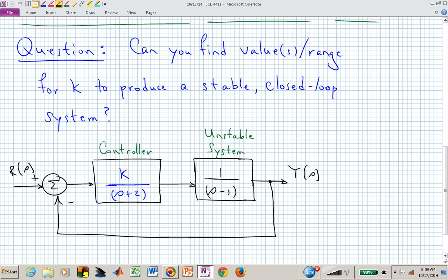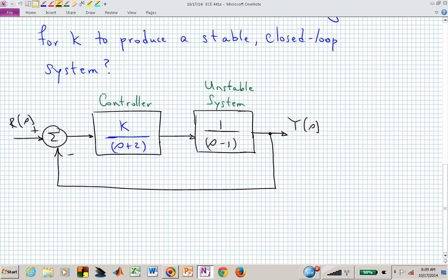This is now trying to motivate, and this one is not as significant or complex as what it could be, and you could still solve a more complex problem with the Routh-Hurwitz criterion. How did we approach this problem? What's involved if we're trying to get the system to be stable? Okay, so now we need to find the poles of the transfer function, and the transfer function that we're after is which transfer function? The open loop, the product of those two, the closed loop. We need the closed loop system to be stable.